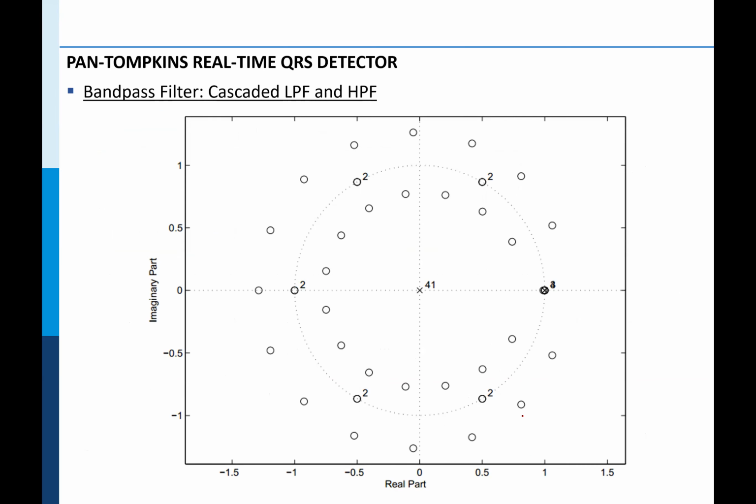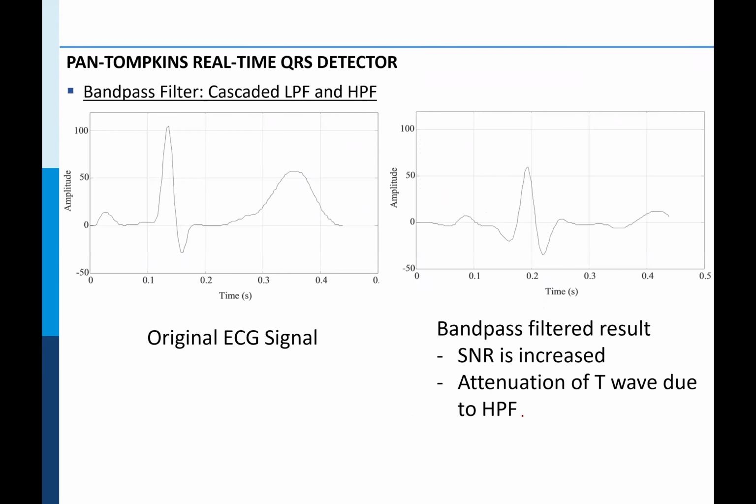So this would be the joint low pass and high pass filters pole zero diagram. And you could see this has a lot of zeros in the system, and there are a few poles, but the poles are not really doing damage to the filter. It's a stable filter. And again, the cascaded filter has also given coefficients that tend to be of integer values.